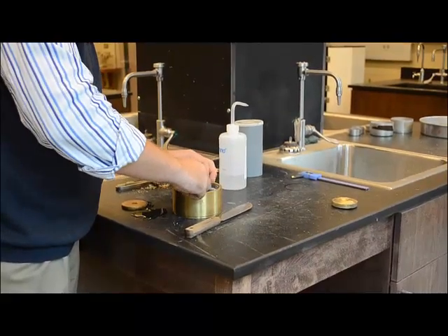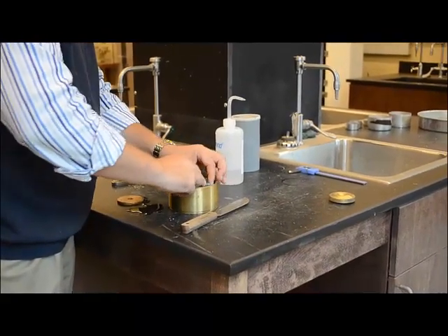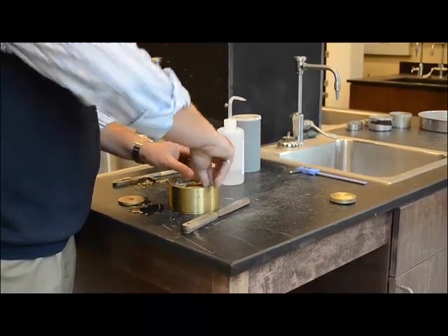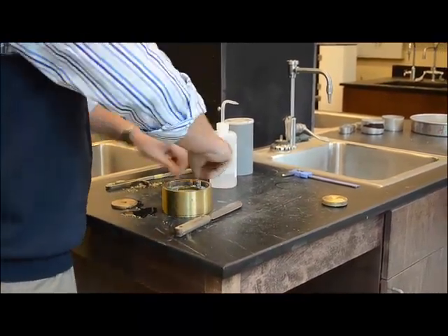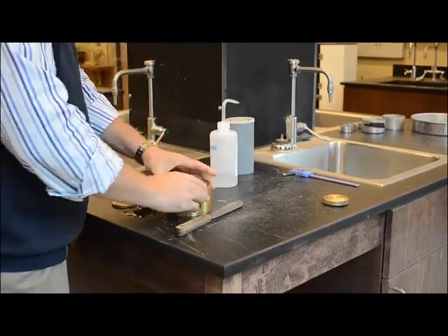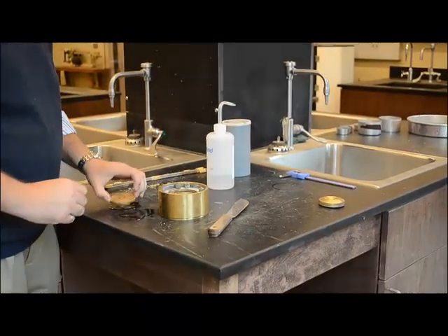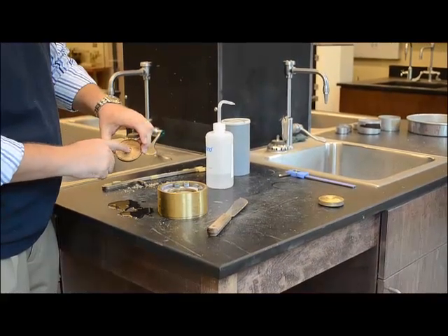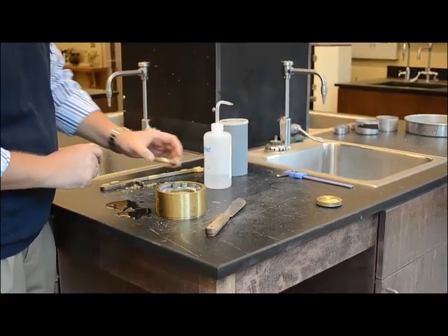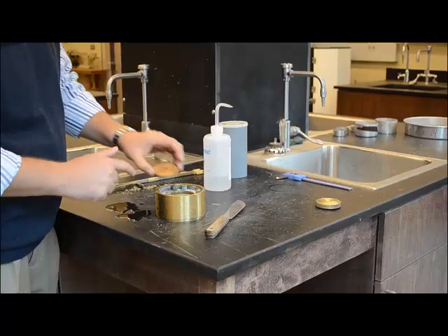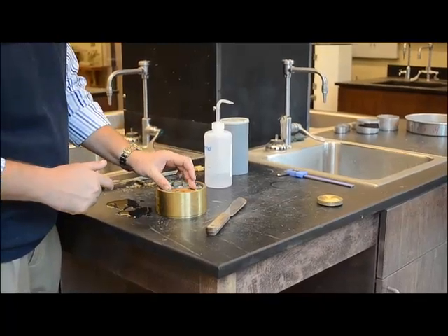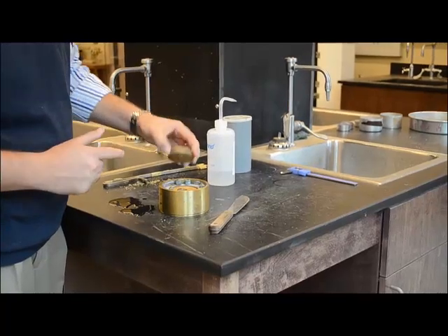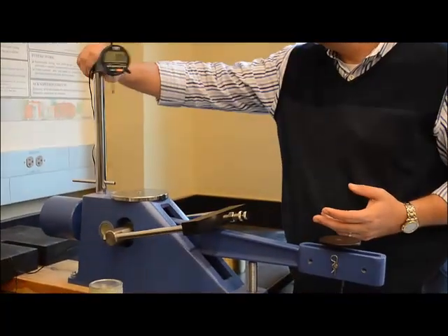Once those knurled nuts are completely installed, hand tight is fine. This is a brass unit, so it's a very soft metal, so you don't want to cross thread those. Be very careful of that too. Then, once that is in place, just hand tighten and put the top porous stone in place. Notice there's a flat piece and then a nipple at the top. You want the flat against the soil sample, because the nipple is the location of the top cap, which fits into that porous stone, so everything is aligned properly.